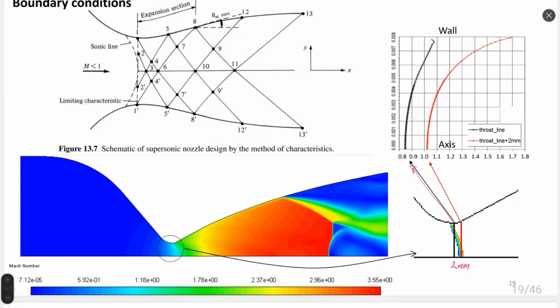The CFD calculation I made was only possible after a calculation of the nozzle by the method of characteristics. So we cannot do CFD from nothing, right? We need to use the method of characteristics to make the profiling of the nozzle, to find the nozzle shape, and only after can we make CFD. But at the same time, CFD can serve for us as a preliminary estimation of flow properties near the throat. So these two tasks can be correlated.